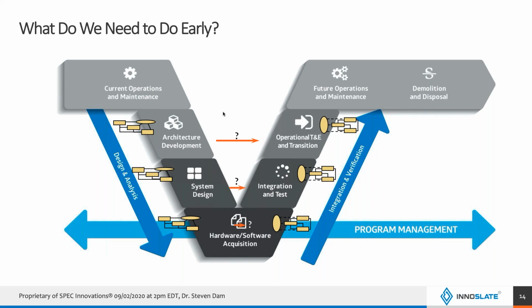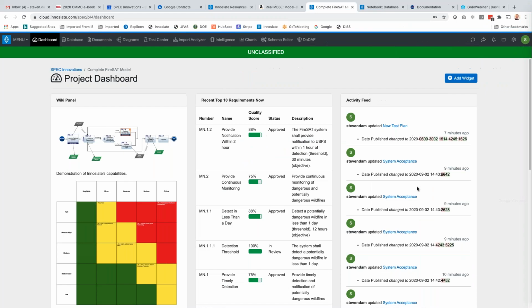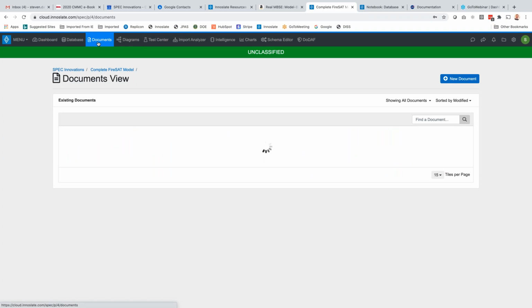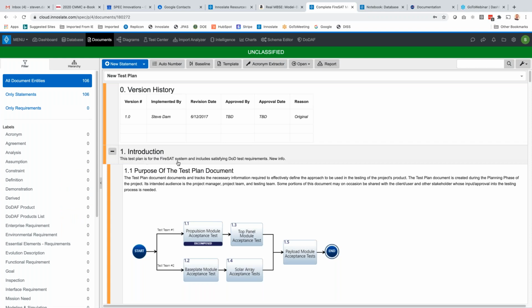My next question is, how can you create and reuse a template? Oh, okay. In fact, the templates in Innoslate are set up in a very simple way. In Documents view, you would go ahead and build your document. And once you're happy with the document, just hit the template button. For the document type you're in, it will create a template in our tool for you that you can then use next time you do new documents for that type of document. And there are custom templates then available. We have more detail about that on the website.